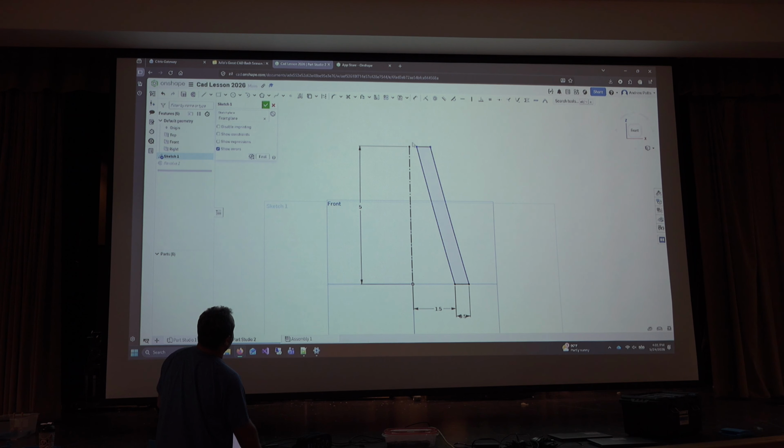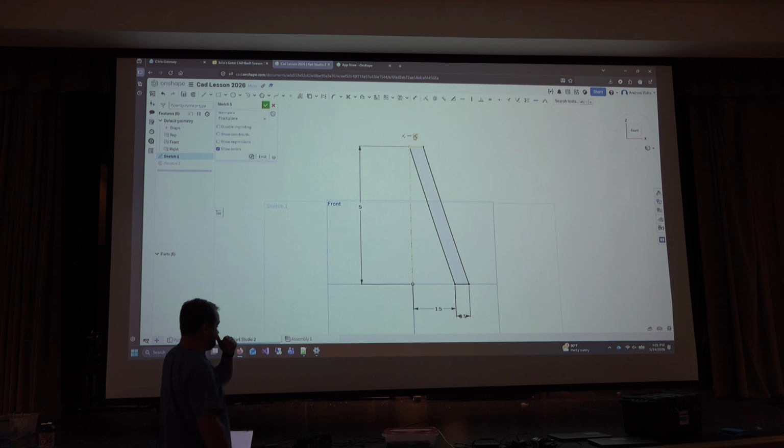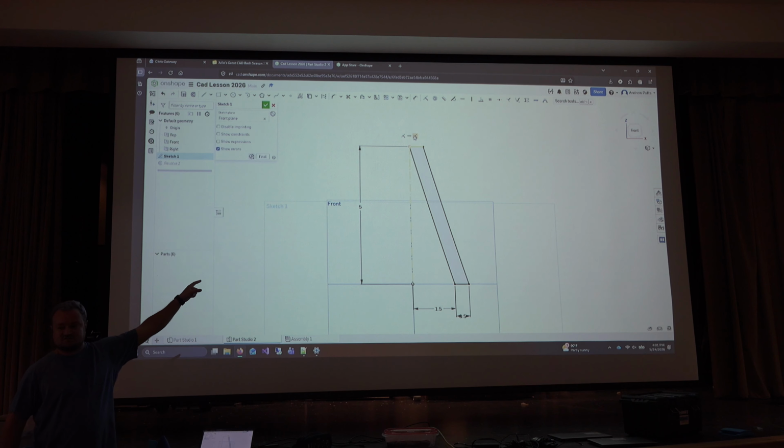Right. So is it this one or this one? This one. Yeah. And we want to remove the one that we want to get rid of. Since we want to move the line away from the axis, we want to find the one where the axis is one of the selected lines, and then one of the other lines is selected, because that's the relation that's currently attaching it to the axis. So that's the one that we want to delete. We want to find the one where the axis and another line is highlighted.